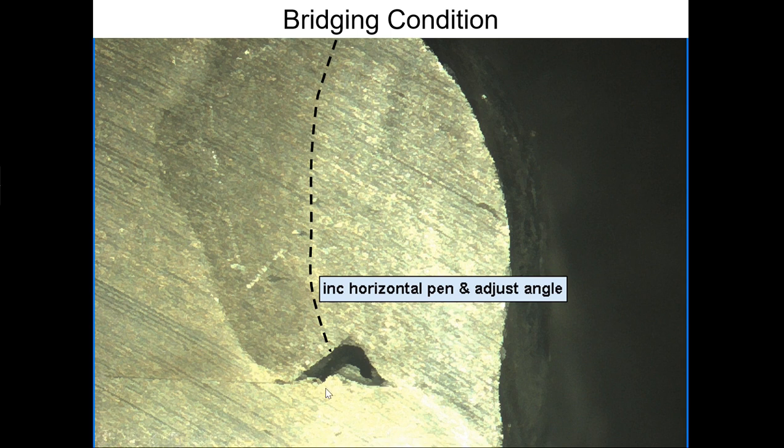Now, this was a chunk of oxide that showed up on top of a weld where a person had said to me, Bob, I can burn that out of there. And I said, oh, okay then. Let's see how it goes. So the chunk of oxide was there, and they went in and put a weld over it, and then I cut it on the spot and showed them that the oxide cannot be melted, and you're lucky if you can even get it to move. Now, this may as well be a hole. Just because that's a chunk of oxide doesn't mean it's doing anything.